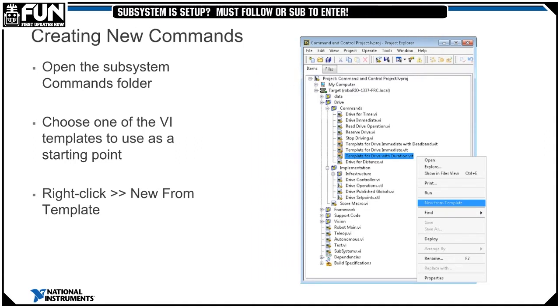What VI actually contains all of your operation code for each subsystem? Each individual subsystem will have this VI. For the drive, it would be called drive blank.vi. This is where you would actually go in, set up your motors, set up your configuration, tell it the commands you want it to have, and send those to the motors.